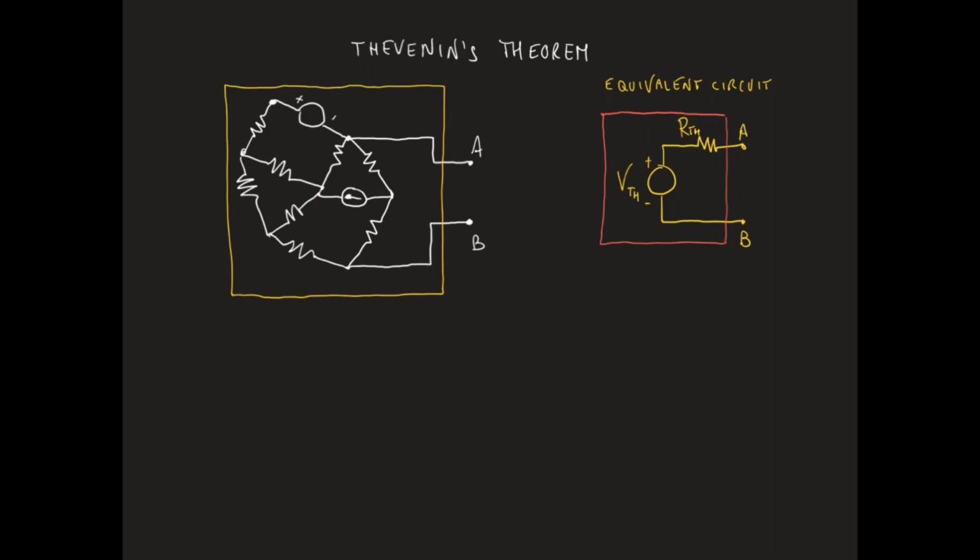Suppose that we can close both the starting circuit and the equivalent circuit inside a box in such a way that we can make the two terminals A and B stick out of the box for both circuits. All we can see of the two circuits are the two pairs of terminals sticking out of the two boxes, and all we can do to understand their properties is to perform some kind of operation on the two pairs of terminals. If the circuit on the right is equivalent to the circuit on the left, there is no way to tell the difference between the two circuits inside the two boxes.